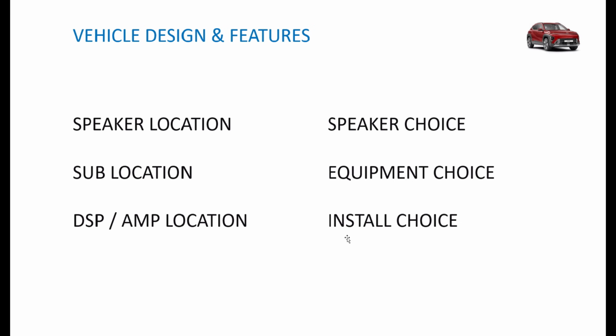and then of course the method of install: ported box, a sealed box, installing things on a speaker ring in free air, or doing infinite baffle installs. Once again, your car will dictate pretty much what you can do, or limit the choices of what you can do. But when you're looking at your vehicle and design features, it's these 6 things that you're trying to consider.